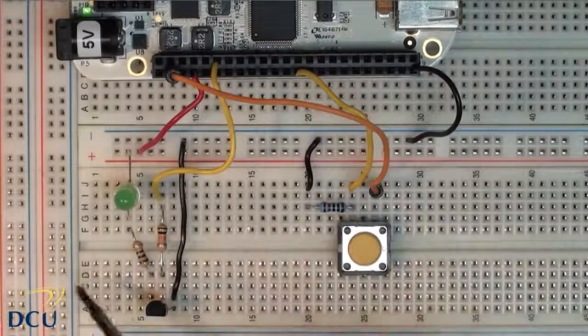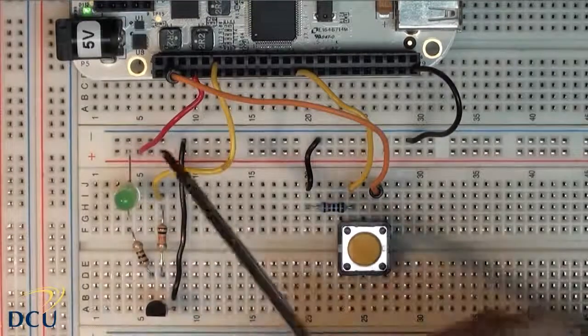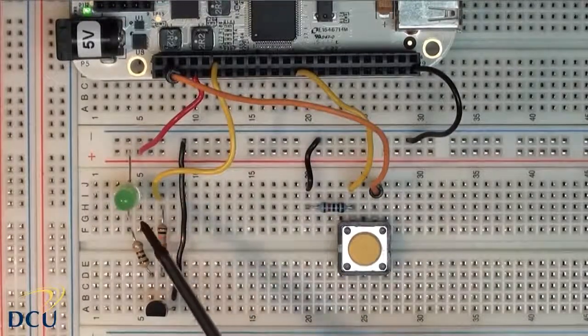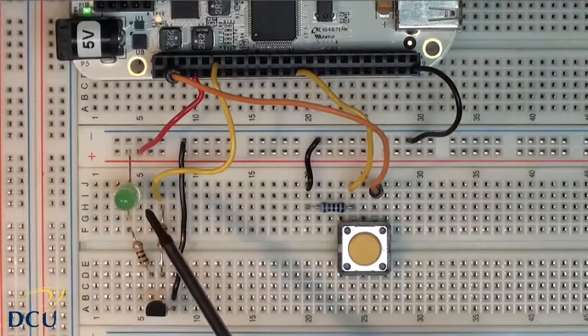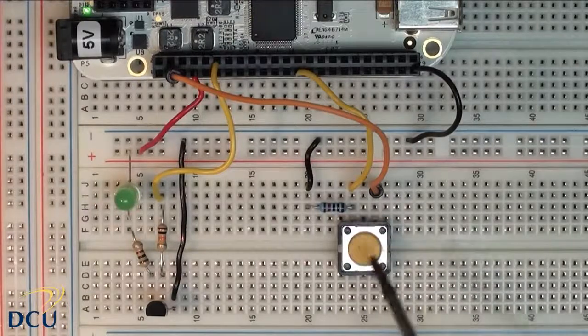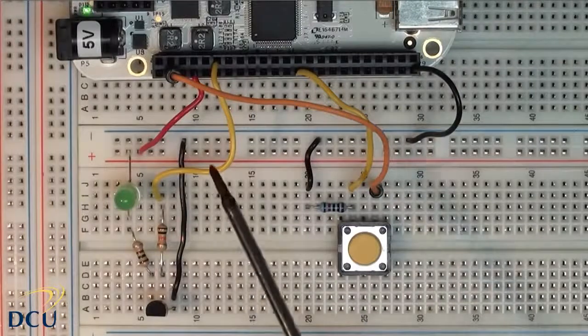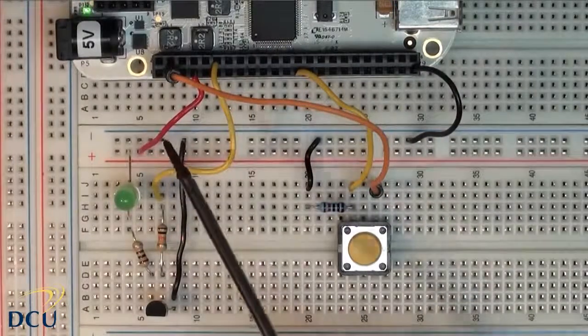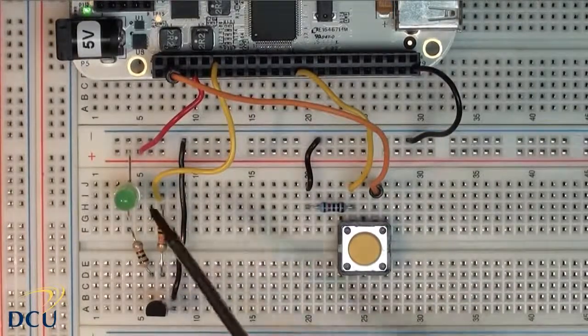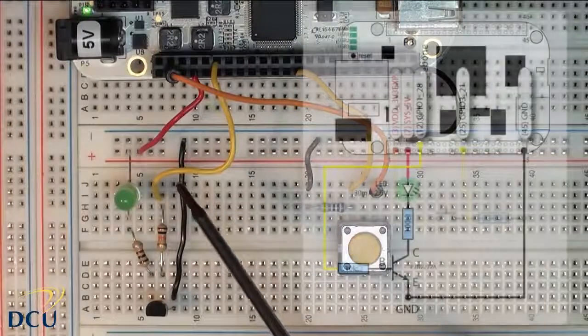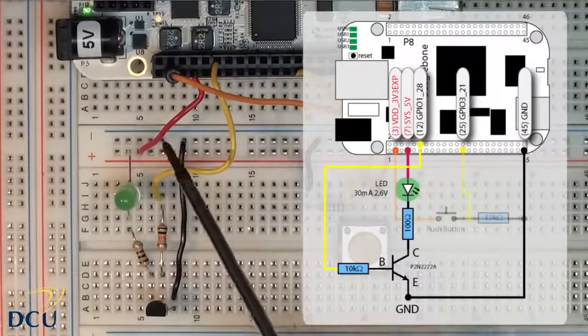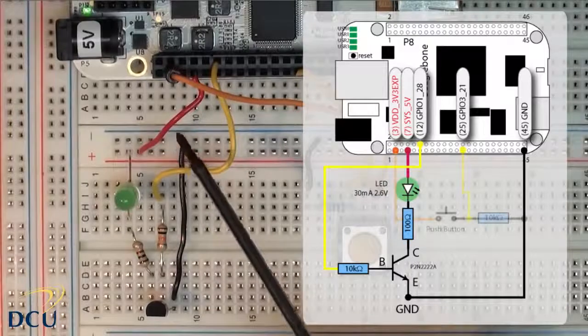You can see here that over here I've got my output side. This is where I'm going to turn on and off an LED using the GPIO pin. Over here I've got my input side using a different GPIO. I'm going to read values into that GPIO using a momentary push button. On the output side, I've wired up a transistor to ensure that the currents are kept low through the GPIO pin itself, and the way that I've wired that is as in the previous diagram.